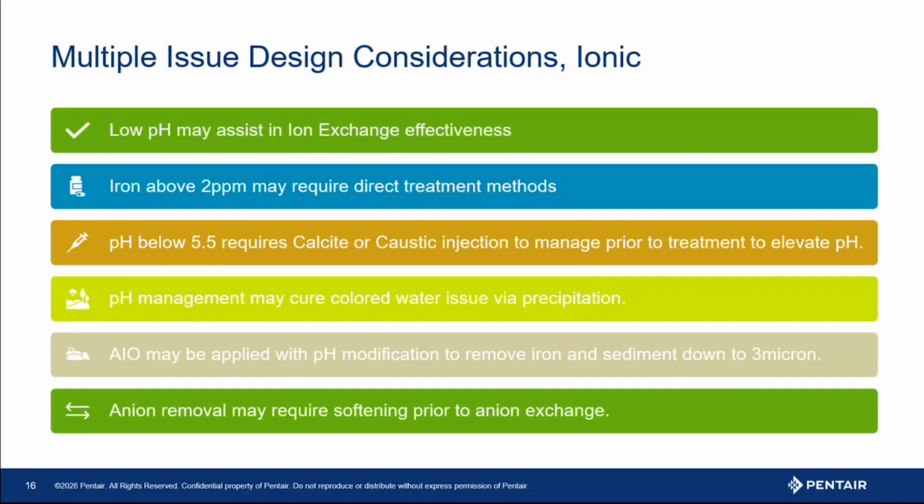Low pH may assist in ion exchange effectiveness, just because our resin cleaners are acid forms. We're going to put that resin back into an acid form, drive everything off of it. And this may help in ion exchange during its normal flow through process and having an exceptionally clean bed that's willing to exchange everything off of it.